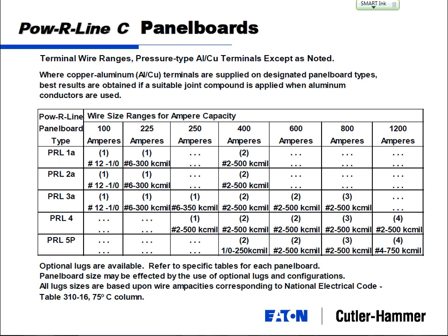You'll notice we've got default cable sizes depending on the panel board and the amperage, but it's important to note the cable size when you're designing. Sometimes you're going to oversize your cables for voltage drop reasons or any other reason. And if you're going to oversize your cables or use a different configuration, always check those.